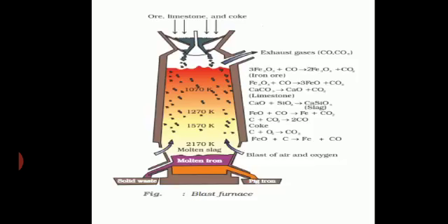I was saying, the economical part of the LD process is that it involves less capital expenditure and is more productive. The operating cost is also very low. It is quite fast and takes only 45 minutes to treat one lot. In one lot, some tons of molten iron can be converted into steel in just 45 minutes.